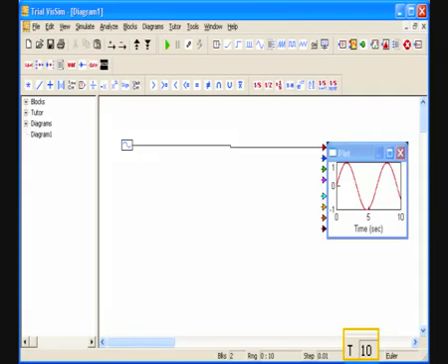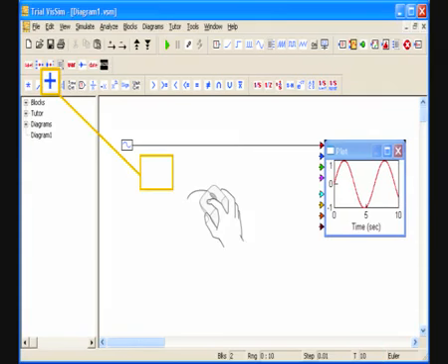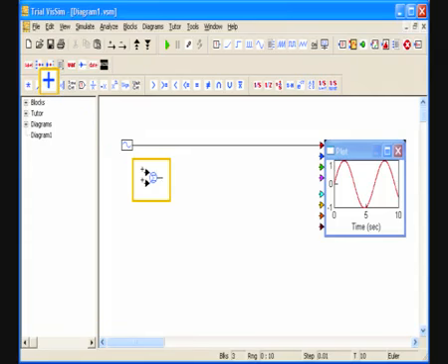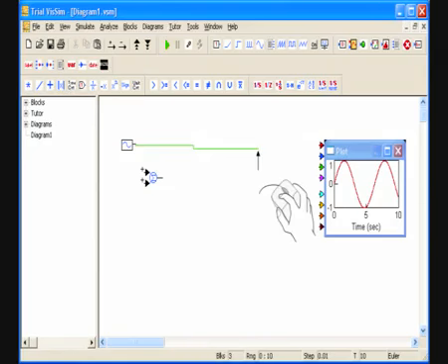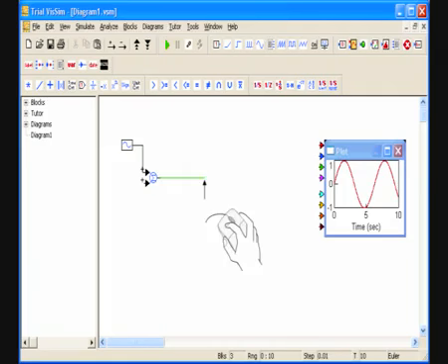To show VisSim's filter capabilities, I have to mess this up by adding noise. You can join signal producer blocks with a sum junction, which again is a new type of block. By doing this and running the simulation again, you can see why engineers generally like to avoid noise. Now and then you see that I've got the status line at the bottom showing the number of blocks that I'm adding to my screen. This is important when it comes to collaboration. The VisSim viewer is free, but there's a limit to the number of blocks that the viewer can handle, which I think is 100.